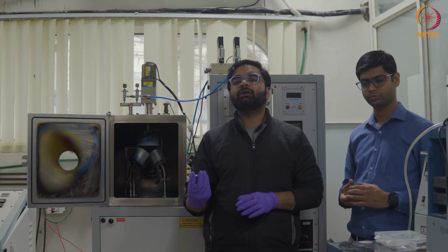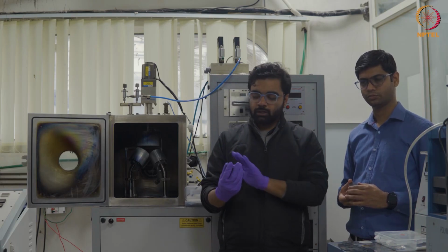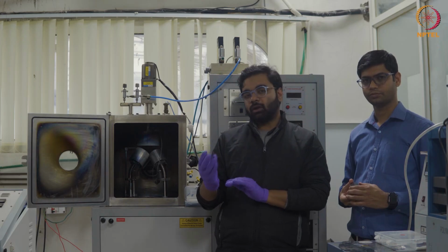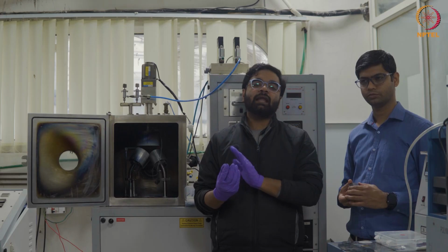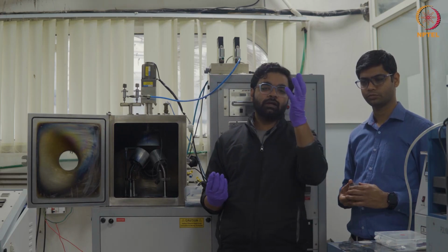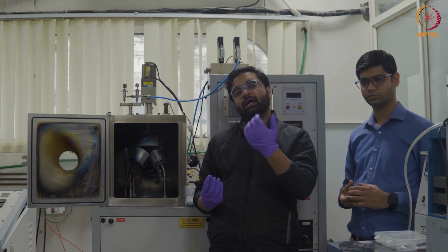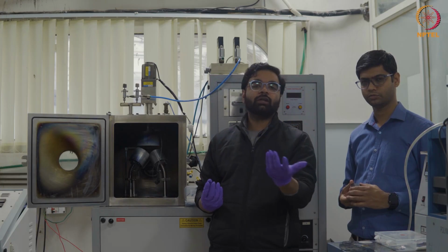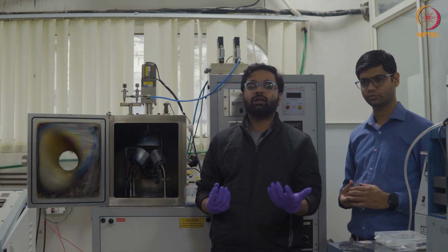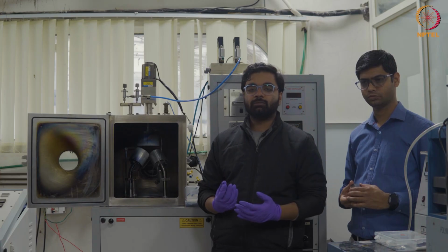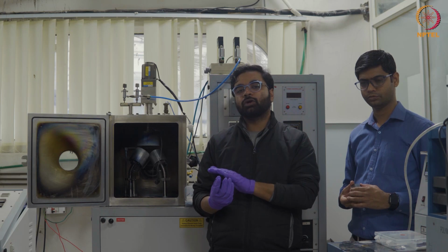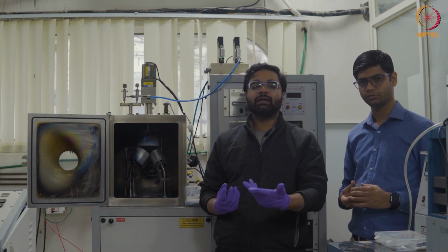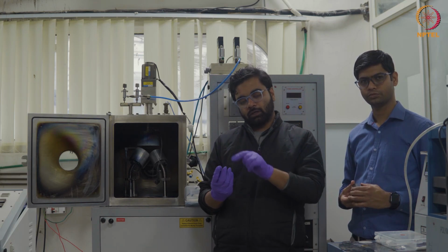It can be done anywhere, but it has to be given a temperature of 80 to 100 degrees Celsius just for the curing of the PDMS layer. Normally, if you don't have a heater, you can keep it in the open atmosphere, but the time taken would be more because it would just take heat from the atmosphere, and the atmospheric heat would be around 30-40 degrees depending upon the place where you are living. So it would vary from place to place. Accordingly, it will take time to dry, or to cure. So what we do is accelerated heating, and based on that heating the curing happens.